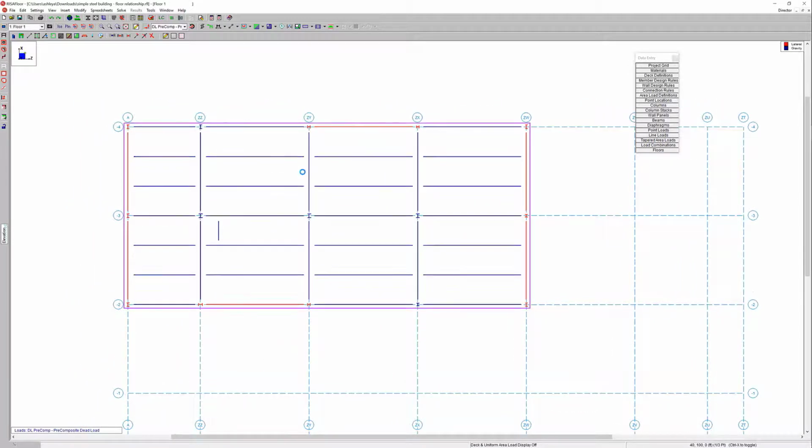So if you recall, when we created floor plan 2, we created it as a copy. So what that means is that any changes I make to floor level 1 are not going to be reflected on floor 2 because it's simply a copy. The copy essentially detaches the two floor plans. They are very independent. Anything that you draw in either of them will not be reflected on each other. So they're independent when you create a copy. So if I come to floor 2, you'll see that that beam is not there.